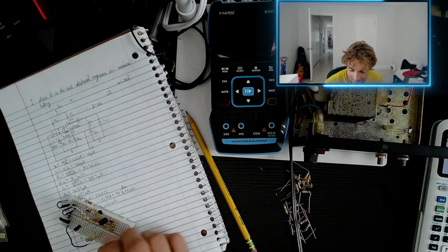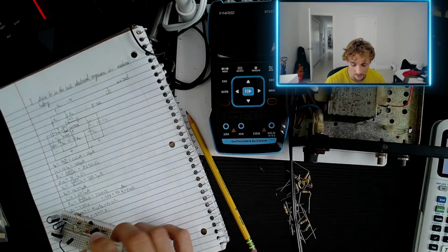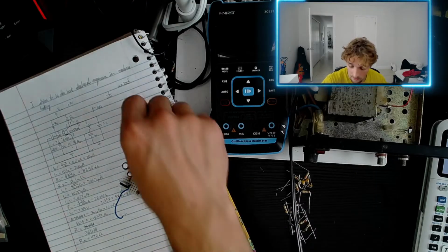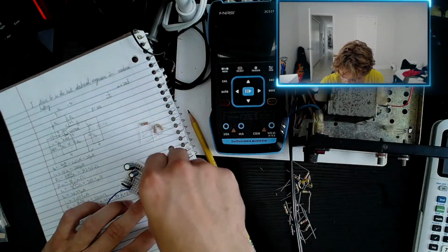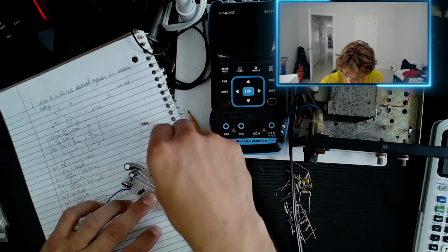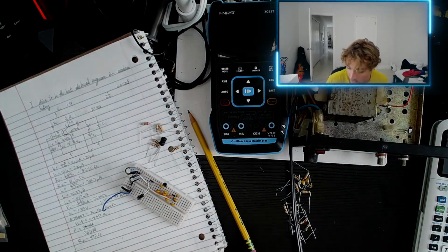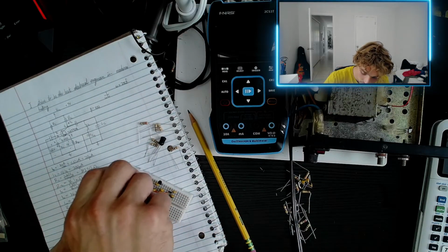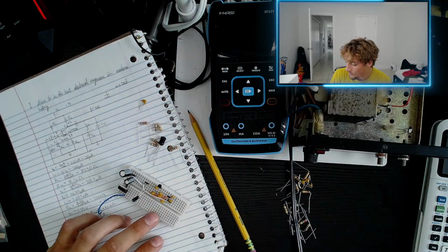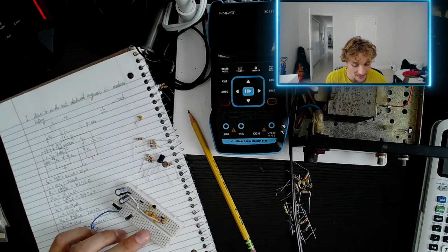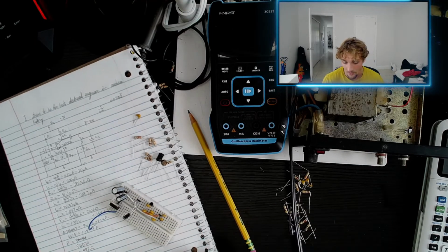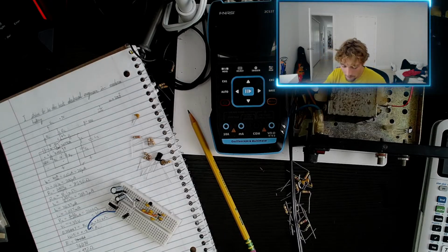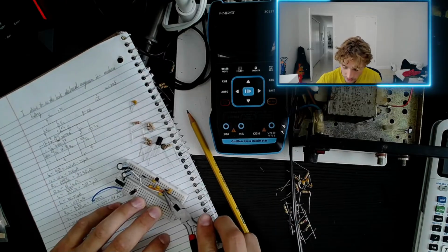So let's go ahead and make this common emitter amplifier, and let's measure some values. I'm going to pull everything apart now. Honestly, I should just pull everything out of here, and short circuit your capacitors, right? We don't want them to hold any charge. I would hope the energy was already dissipated through the resistors connected in the network, but you can never be sure, so rather safe than sorry. So we're going to short circuit all of these and ensure.